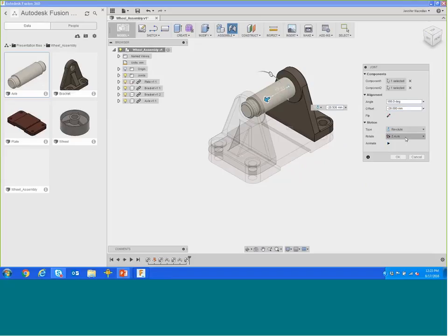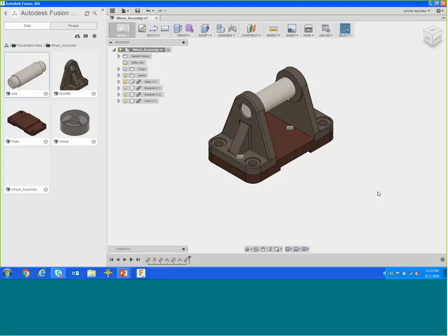One thing I just want to flip here to show you is the rotation axes. The Revolute type removes all translational movement, but allows for one rotational movement, and you can actually define which rotational movement that is. By default, it defaults here to Z, so I lucked out, but if you ever had to change that, you could go in and pick which axes you want to allow it to rotate in. Okay, as you can see those are all completely wrong, but we want to leave it with the Z axes and give us the rotation we want. So we can click OK here, and we have our assembled components.